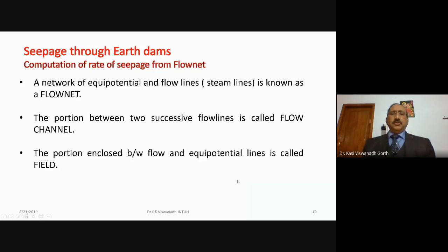Yeah, this video mainly depicts two issues: a dike model, the simulated study with the different runs, and how the seepage line would be through an earth dam section. Two cases have been taken. In the first case, you have an earthen embankment directly, and how the seepage is taking place is shown through the movement of an arrow. The second part is that by providing a small central impervious core, how the seepage line is getting changed. So these are the two things which have been shown in the previous video.